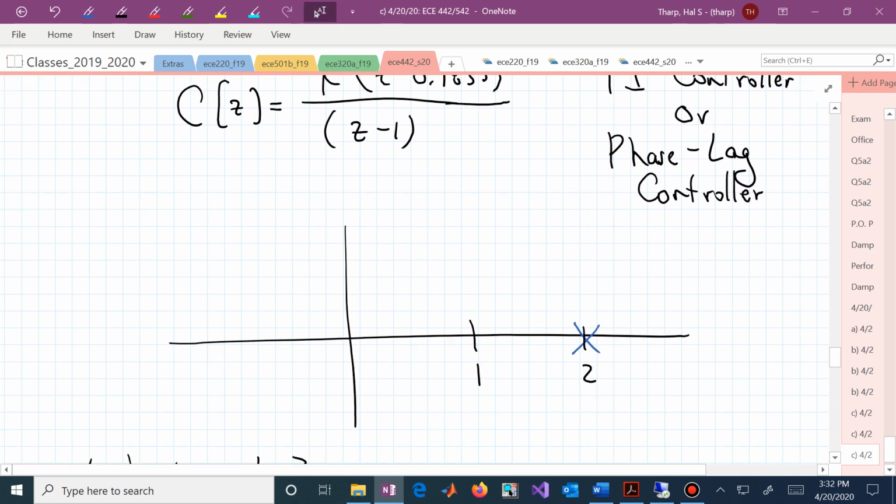How does that play into our design? Well, here was our original unstable system. We had a PI controller. We had then that fixed pole at z equal to 1. We now have a 0 right there, and oh boy, what is that? That's our two poles to the right of a 0. These two branches, one goes right, one goes left.